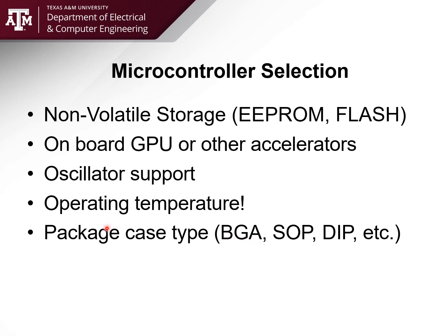Package, case, and type. If you're dealing with microcontrollers, this again is mostly aimed at my senior design students. If you're actually going to be building, you need to consider what the type of package is. Everything we've seen, like with op amps and stuff, we're dealing with DIPs, dual inline pin, SOPs, small outline package. This is a surface mount package. These are fairly easy to solder. In fact, DIPs are extremely easy to solder and actually use on a breadboard.